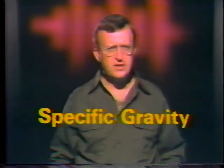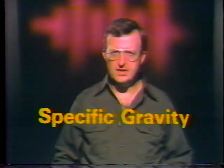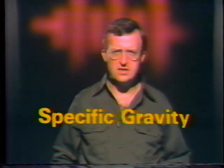Specific gravity is the ratio of the density of a substance to the density of water. So when we measure the specific gravity of the electrolyte in a cell, we can find out how much acid it contains. Acid is denser than water, so if we get a high specific gravity reading, we know we have a lot of acid. A low reading means a much smaller amount of acid.